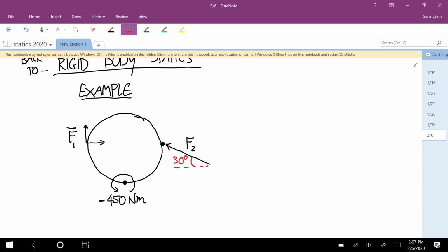Which, on which? On the couple? Yeah. The moments you have a counterclockwise arrow. Right. That indicates positive. Yeah, so that's the same as if I had written this with a negative, going this direction, and this was negative F2, that would be the same thing as F2 going this direction. Because if you multiply any vector by -1, it switches the direction. Think of that as something you're multiplying to a unit vector.